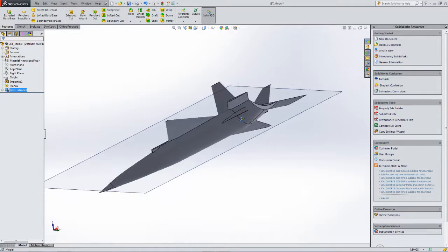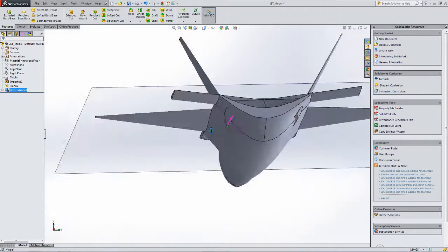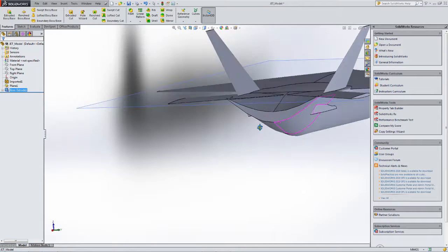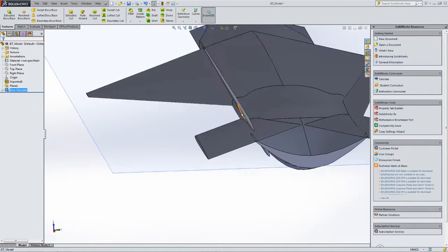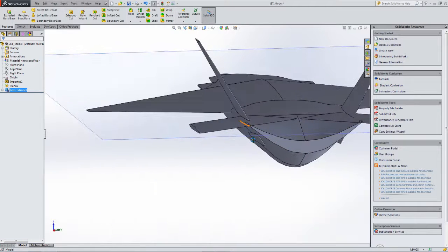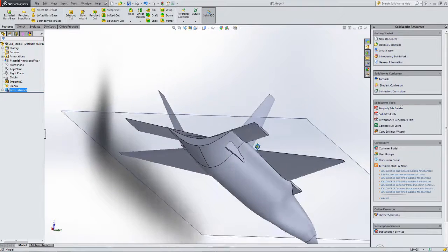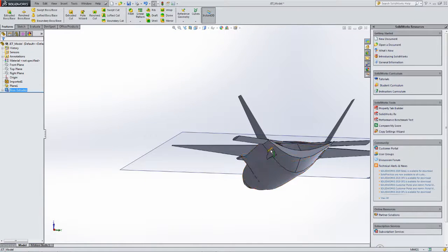So one of the issues is we have these, the bottoms of the vertical tails, and that's an artifact from Jet. Jet always draws the vertical tails from the 0 height line, but then in order to get the vertical tails to be out at the edge of the fuselage, we had to move them out pretty far. We want them out here when they exit from the fuselage, and that left these pieces down here. We could just ignore them. They probably won't change the wind tunnel much,